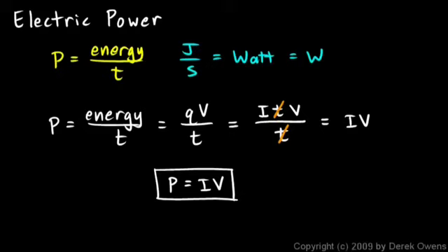That means in any electrical device that has some current flowing through it and has a certain amount of voltage is also using energy at a certain rate. That's the power. And that rate of energy usage is always current times the voltage. Now we'll do some examples with this, but hold that for just a second. I want to do a little bit more with this equation first. Take this equation, P equals IV, and let's take Ohm's law. Ohm's law says that V equals IR.